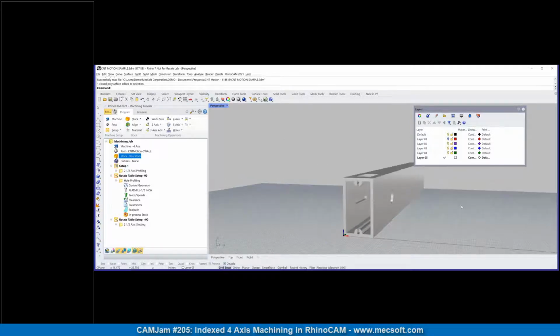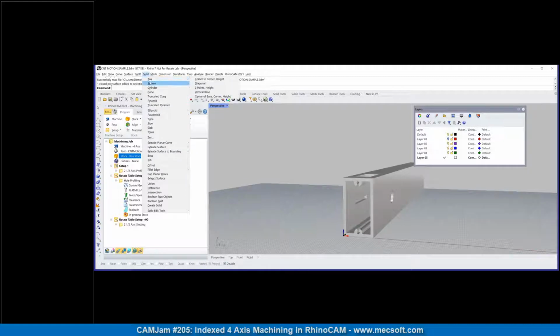And I was playing around today trying to figure out how to draw the solid object like that, like you're showing in RhinoCAM, but I have the outline of our metal in there. I just was trying to figure out how to make it solid so I could do the machining processes like you're showing now. Yeah, all you would have to do is do an extrude.